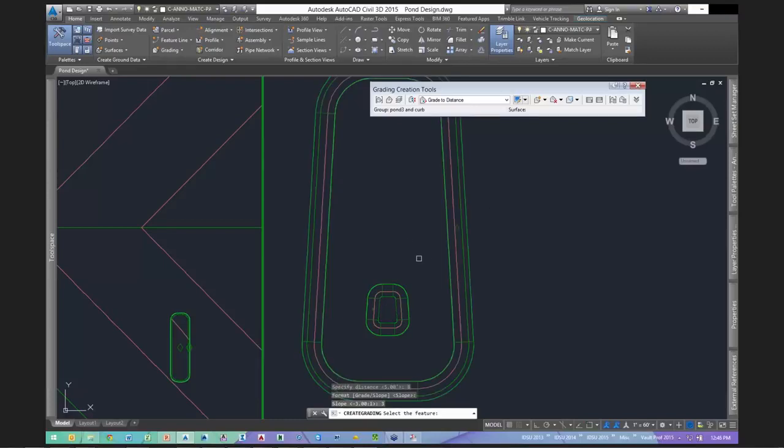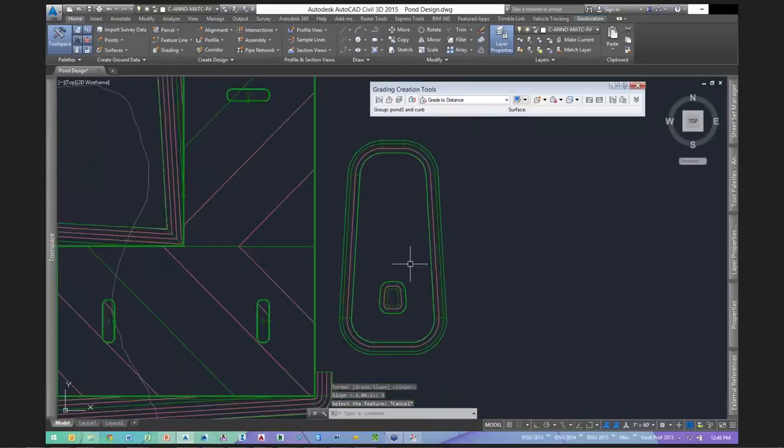Okay. So from right here, what is this area in here? This is an open, or excuse me, a closed space within the same site. Anytime you have that, it means you can create an infill. And if I click that infill button and hover over this, you're going to see it highlights, and it draws in or fills in that area.